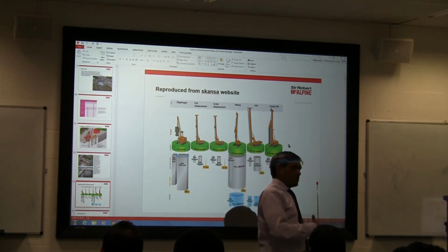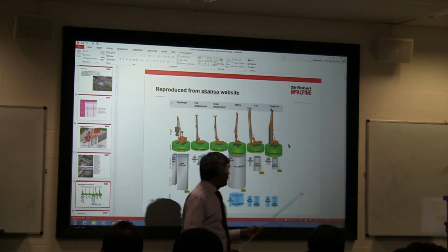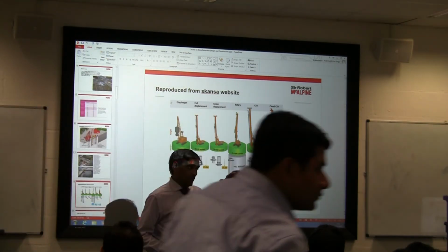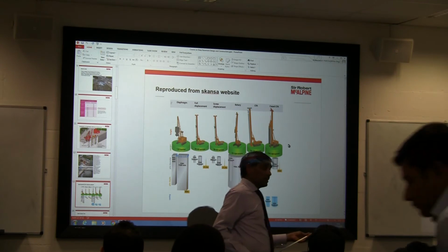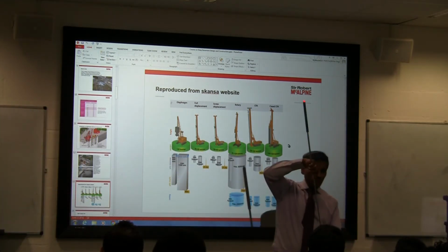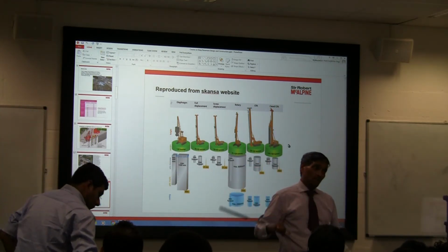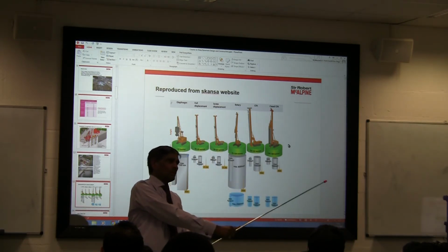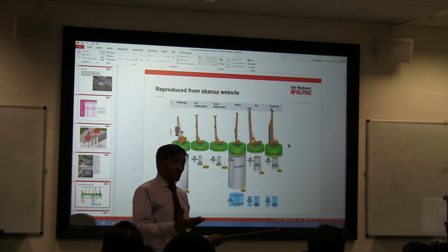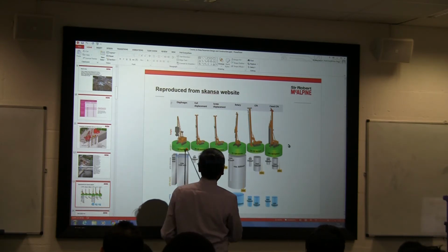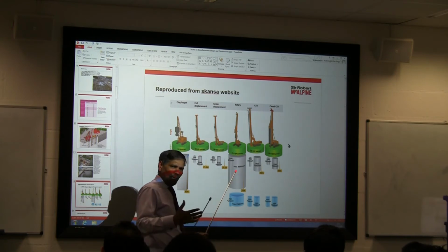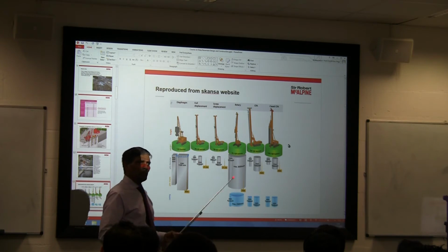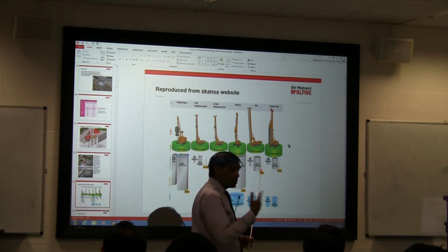So you have to build some stuff. When you do the demolition, whatever rubble is there, you need to bring that and make sure that the stability of the piling rig or the diaphragm wall rig is not at all compromised. Because remember, we're doing very large operations. If it falls, it's going to. There have been cases where the whole rig fell onto the railway track. So stability is very important. So for the piling mat, the mat that the rig is going to sit on in temporary condition, you have to think about what sort of pressures we are generating under the tracks and what material we need to put under the tracks before you start doing anything.